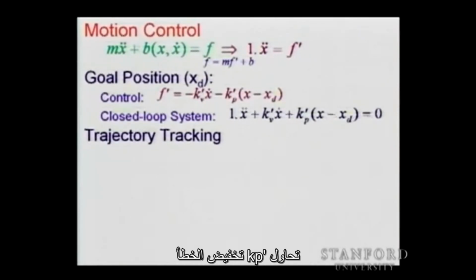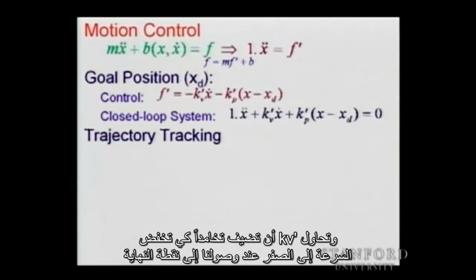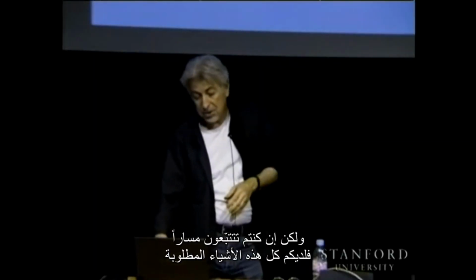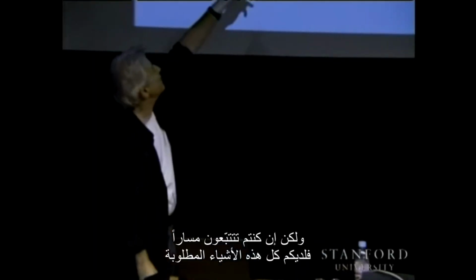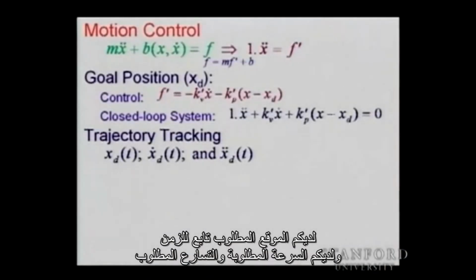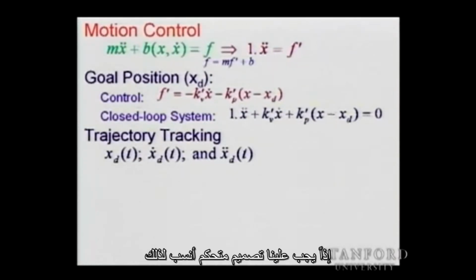Kp prime is trying to reduce the error, and Kv prime is trying to put just damping to bring the velocity to zero at the endpoint. But if you are tracking a trajectory, you have all of these desired things. You have desired position, function of time, desired velocity, and desired acceleration. So we need to design a controller that is more suited for this.